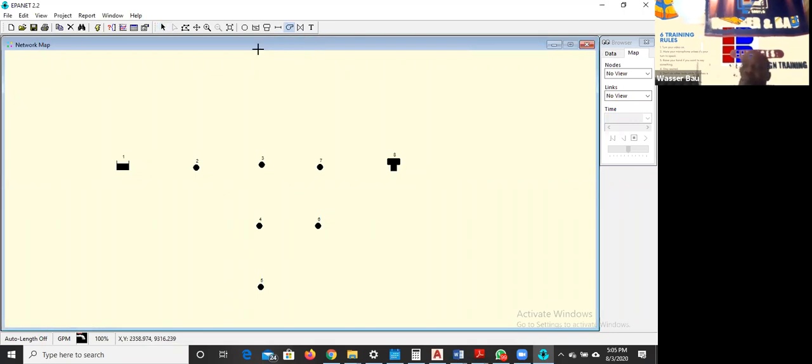Click on the pump. Then come and click on the center of this reservoir. Once you click on it, the cursor will turn to a pencil. Then I'll come to the center again of this node 2, and I'll click. Then to add a pump there. If you click and it didn't go off, know that you didn't get it because the pipe is drawn segment by segment.